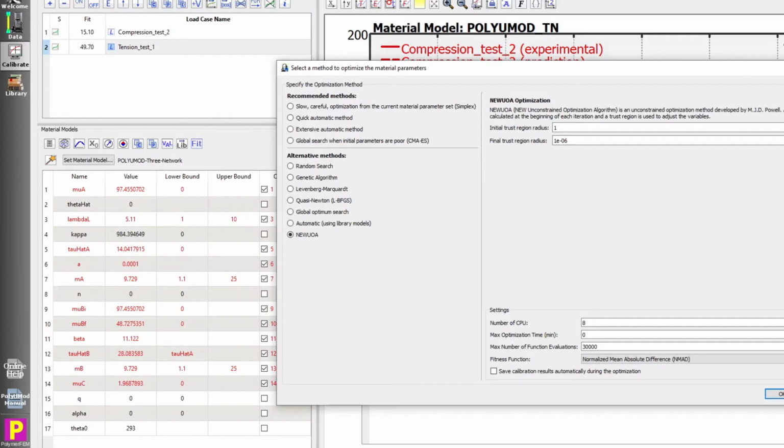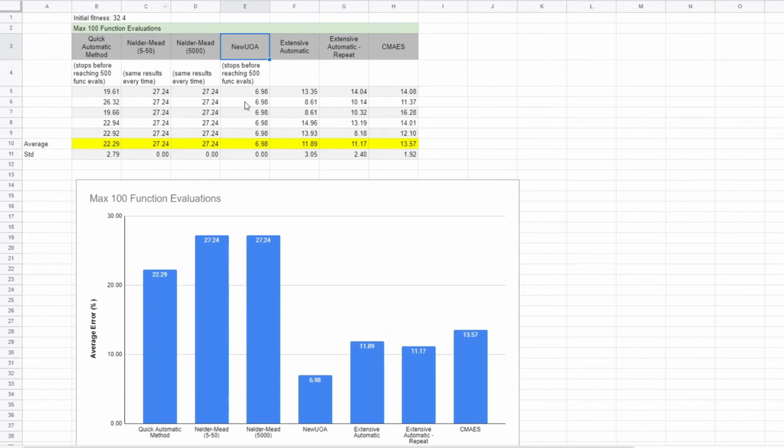I didn't remember that, I didn't realize that. So this is the Powell method, an unconstrained optimization method. And I usually don't change the trust region or the trust radius values there. They are usually good enough the way they are. But if you run that, it converges very quickly. It's an excellent method for rapid convergence from a starting point. And that is my preference for that.